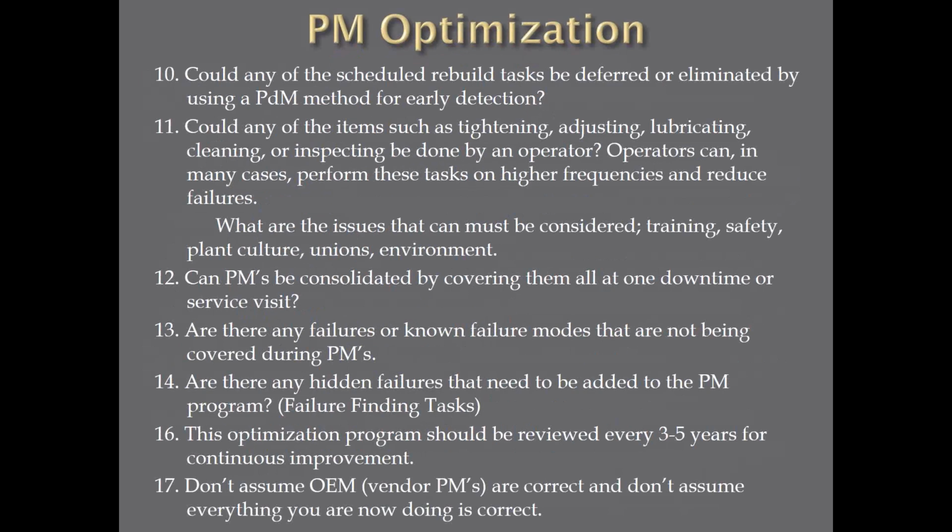The plan I was telling you about, where we trained all the operators to do inspections, they become highly effective because they know what they're doing. They're trained. Are there cultures there, like unions or a plant culture that's been in place for 30 to 40 years? Those are all things you have to work on to get your operators involved in doing some of these minor inspections. Now, they shouldn't be rebuilding gearboxes, but can they do a lube test? Can they at least touch the component? Can they listen, use their senses, and do these PMs?